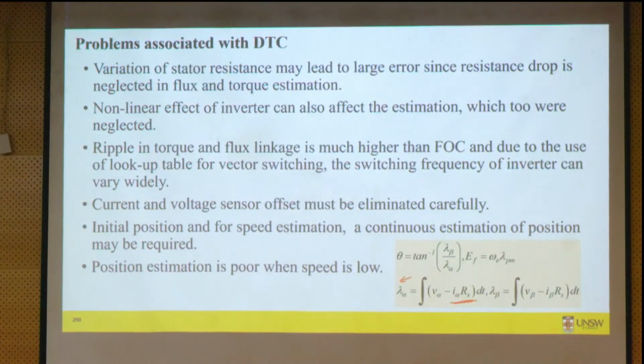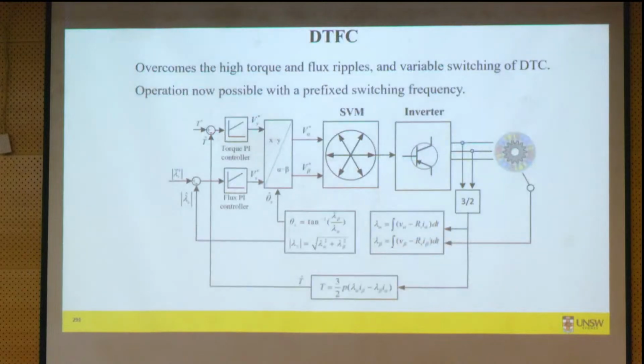Okay, so these are some of the major or key problems, which have then been resolved by changing the switching table to an SVM technique and changing the hysteresis controllers to PI controllers.